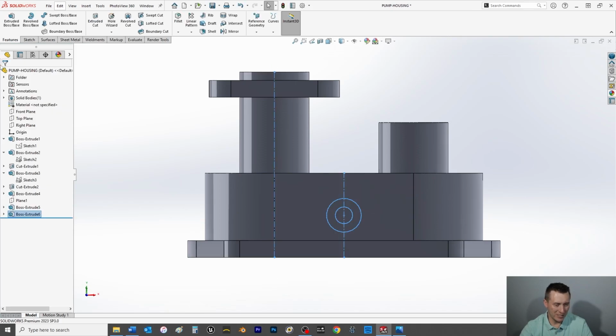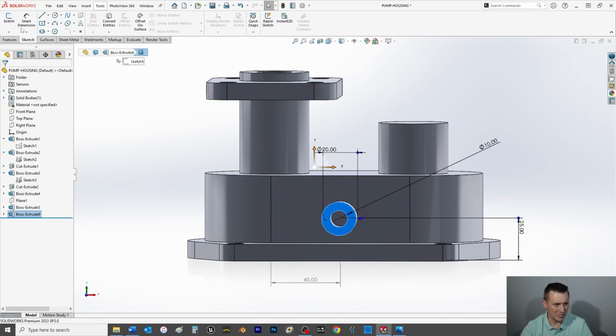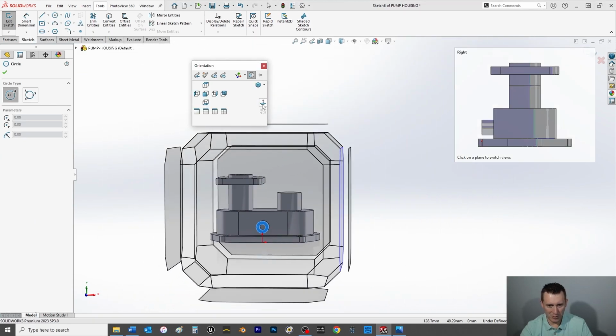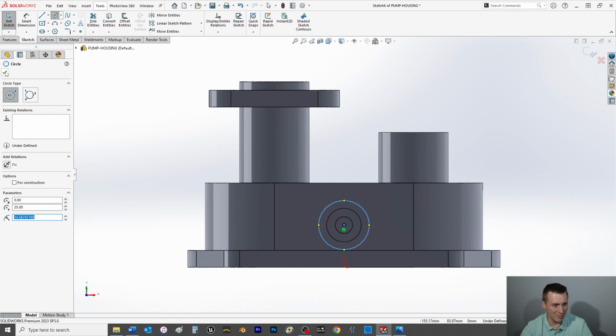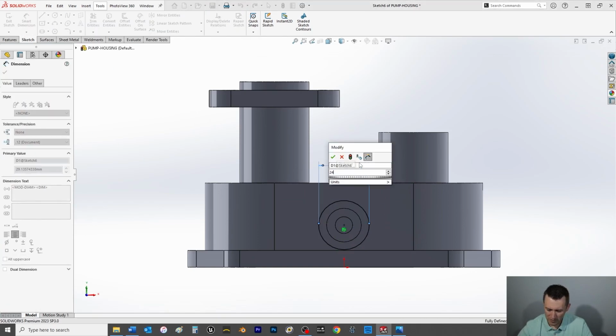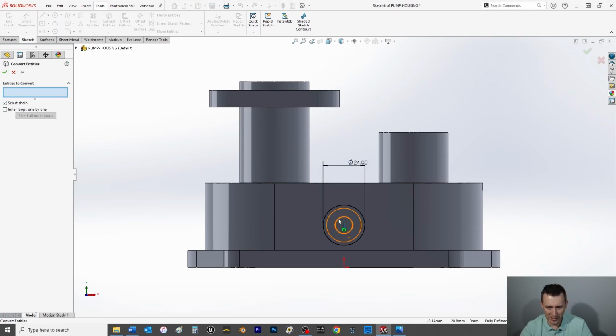These are the inlet and outlet, or I'm calling them the Mario pipe. We're going to select this face here, do another sketch, and we're going to bring it normal to so I can grab that center point there. This is going to be a diameter of 24, and then we're going to finally do a convert entities and pick up this ID.